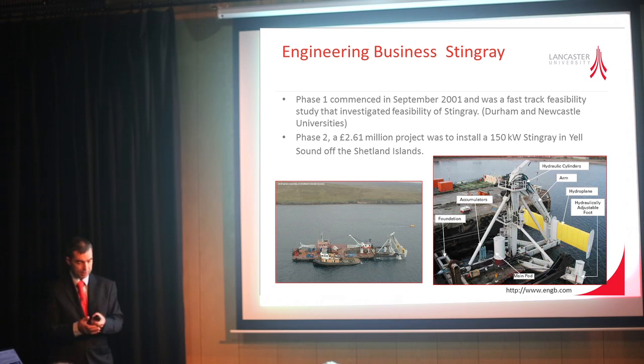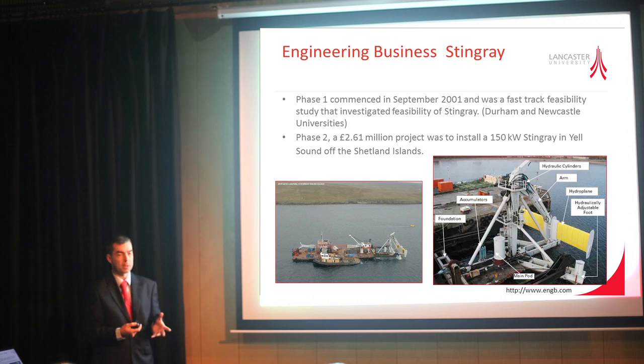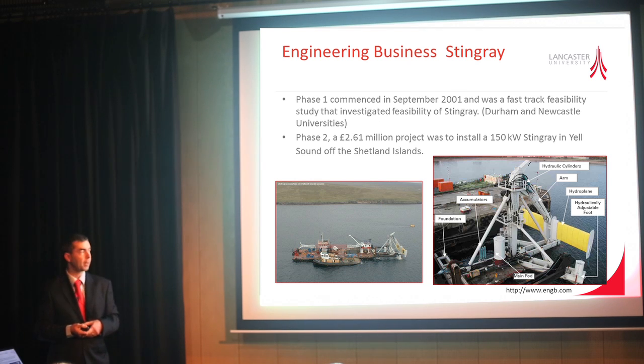So, some of the device types themselves, in terms of tidal stream. This is one of the earlier devices, the Stingray by Engineering Business. They made a prototype system that they deployed off Shetland. Essentially it consists of a hydrofoil, essentially a wing, similar to what you'd find on an aircraft, on an arm. As the tidal flow flows over the wing, it generates lift. That causes the arm to go up. It then pumps hydraulic fluid down through that. That pressurised hydraulic fluid is then used to generate the electricity.